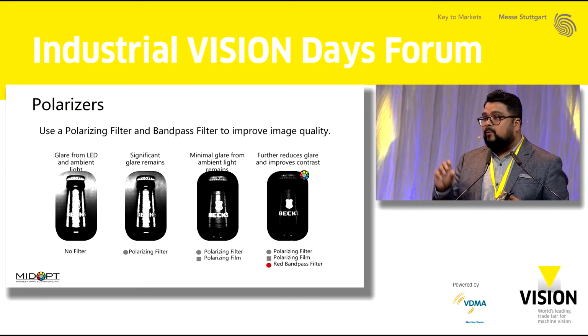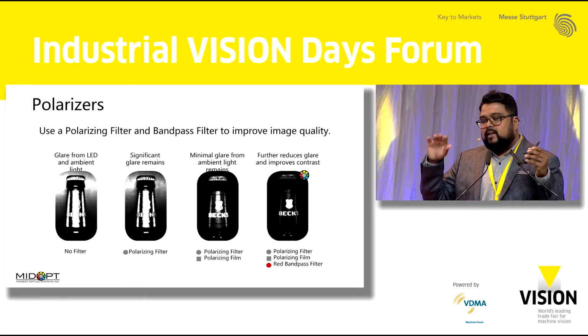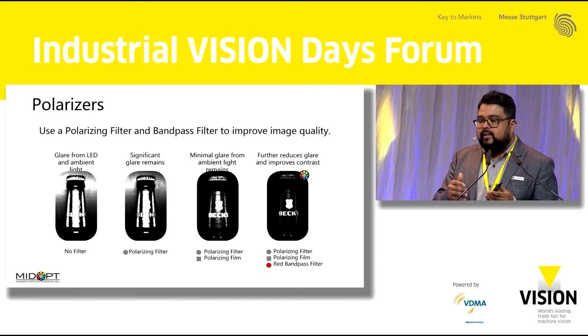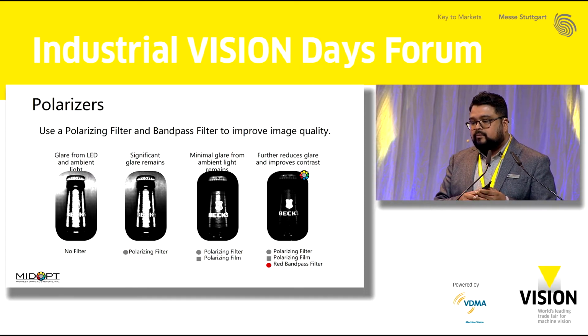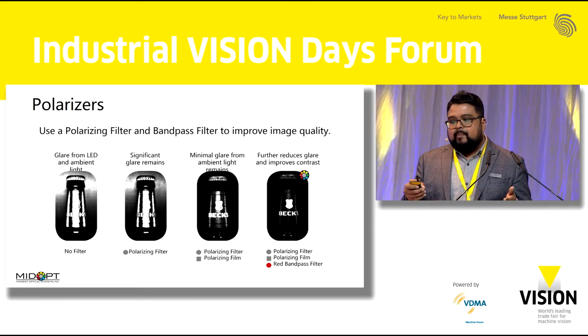Finally, I use a red bandpass filter to limit some ambient light and to help reduce the reflections on that label. So polarizers, great way to combat and help reduce glare in your applications.